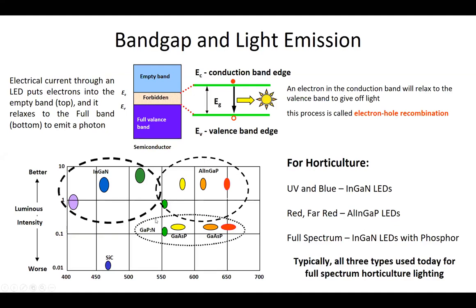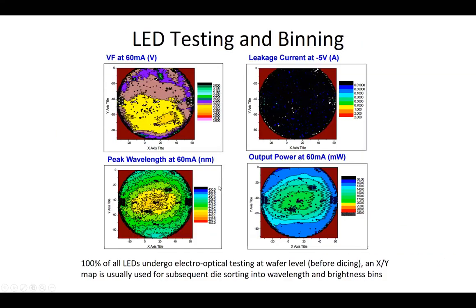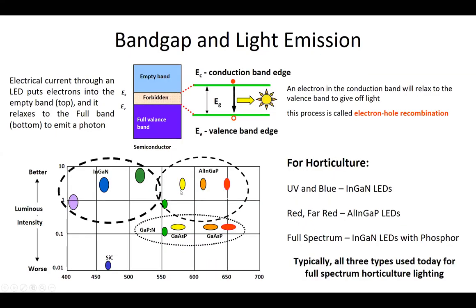The brightness was very, very low. And then from 1962 to about the 1990s, the aluminum, indium, gallium phosphide class of light-emitting diodes were made. They're very, very bright, and they can make typically the colors red, orange, and yellow. They're not very good at making green LEDs. But if you have a keyboard or a stereo or something like that, and it's got a little green indicator light, it's the aluminum, indium, gallium phosphide, or AlInGaP, diode that is used to make the green.